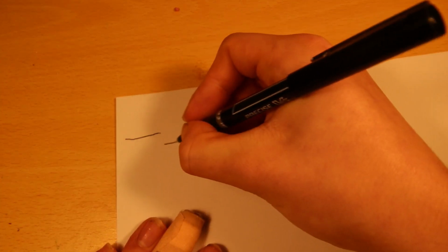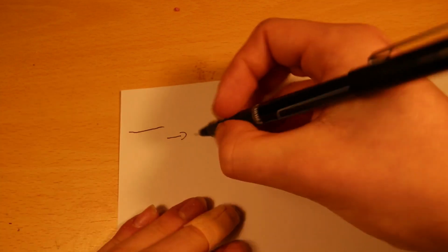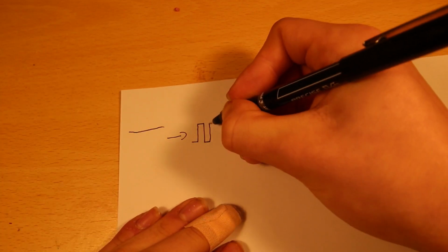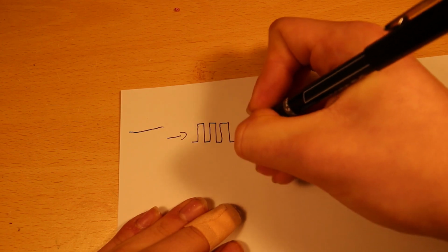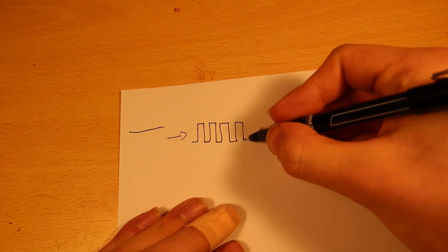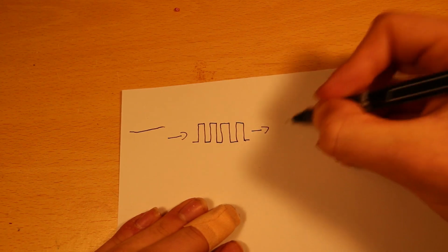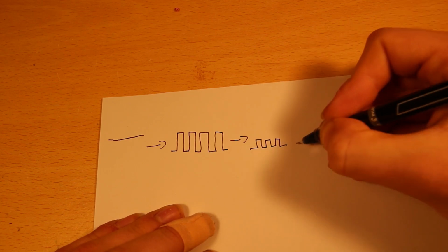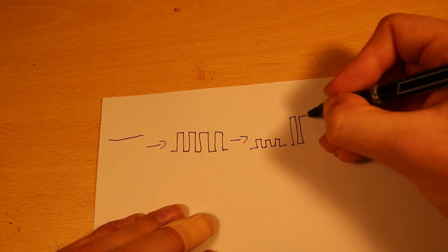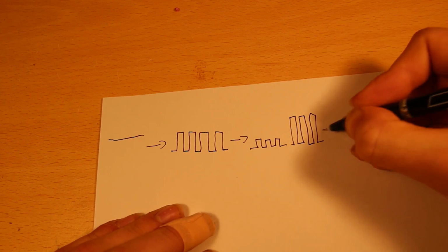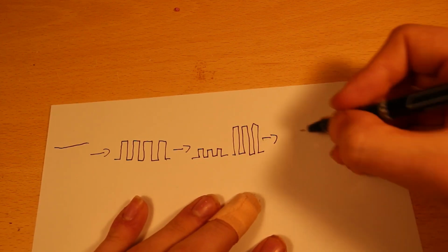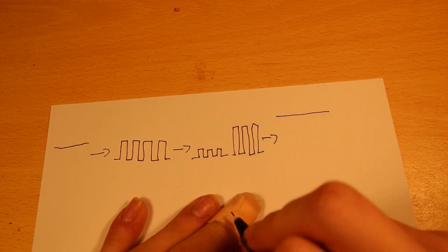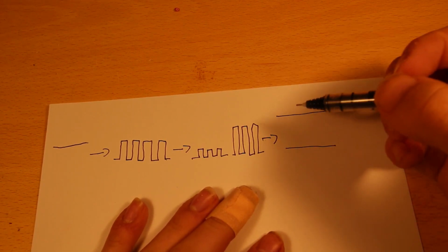Actually, what happens is you feed in your DC waveform like this, and then inside the machine, or inside the module, it will be chopped into a square wave like this. Usually it's a square wave, they don't use sine wave inverters for this kind of thing. Into a square wave. That then gets transformed into a lower voltage like this, or into a much higher voltage like this, and then they turn that into a DC output again, but a much higher one, or a lower one, depending on what you're doing with the power supply.